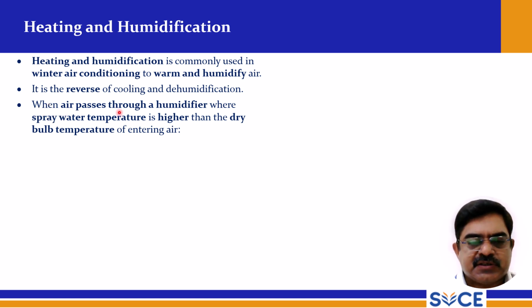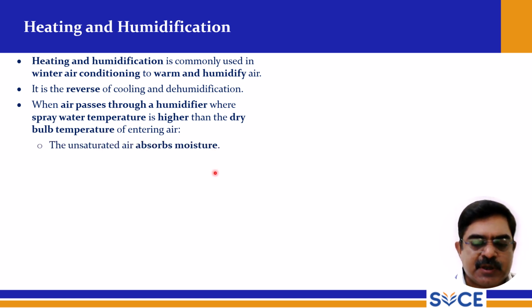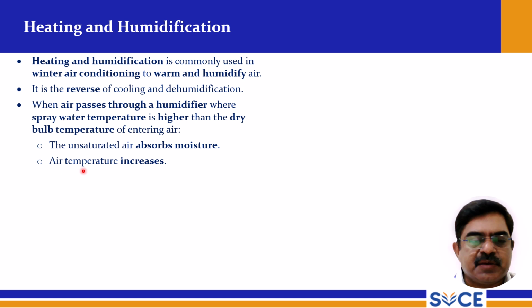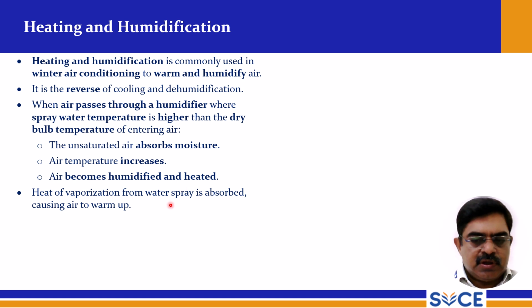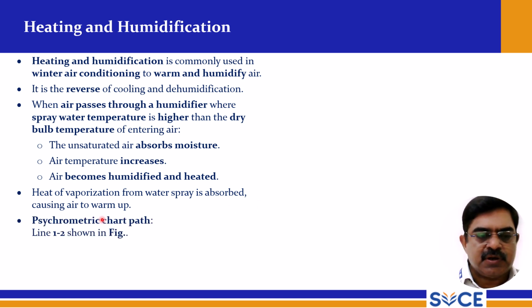When air passes through a humidifier where the spray water temperature is higher than the dry bulb temperature of the entering air, the unsaturated air absorbs moisture and air temperature increases. Air becomes humidified and heated. Here the heat of vaporization from the vapor spray is absorbed, causing the air to warm up.